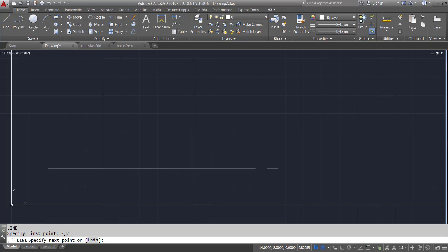And if you remember, in the grid and snap dialog we had set the grid to 1 inch. So you'll see that the cursor snaps in at the half point between each of those grid lines. So I can drag this along horizontally, and it's being forced to snap to the 1/2 inch points in the snap mode.